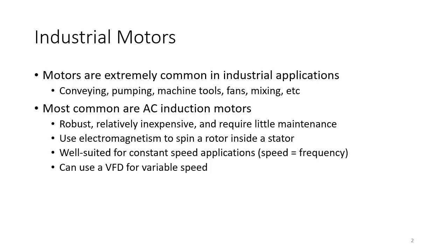Industrial motors are extremely common in industrial applications. They're used for driving conveyors, pumping, machine tools, driving fans, driving mixers, and a variety of other applications. The most common are AC induction motors. AC induction motors are robust, relatively inexpensive, and require little maintenance.